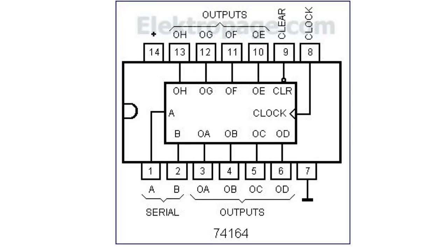So here's a little shift register. It's got a serial input, and it's got parallel outputs, and it's got a little clock. You could use the serial clock for that. And so this would be a perfectly fine slave for an SPI interface.